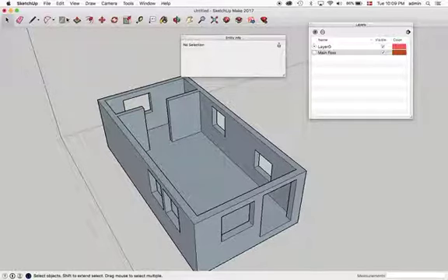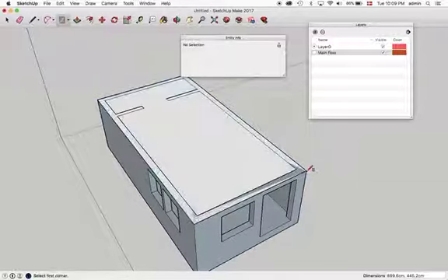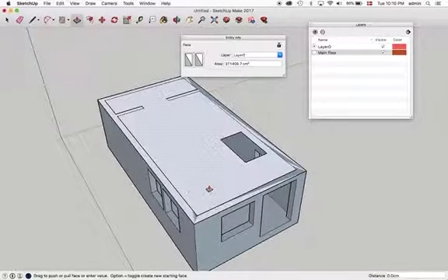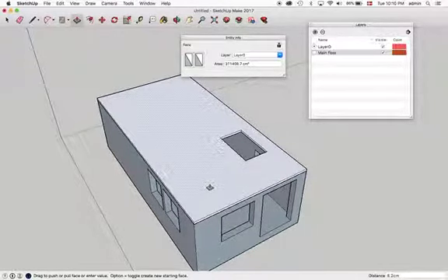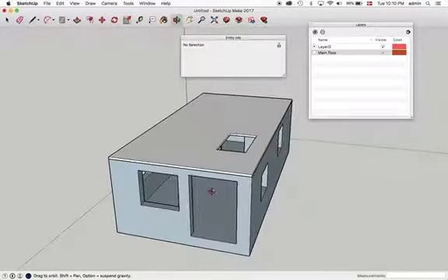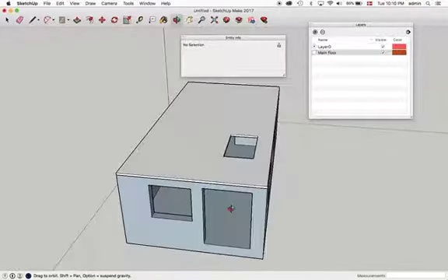Now I'm going to put a mezzanine area on the top. I'm just going to draw a rectangle across. I'm going to draw a trapdoor next to the door, I think, and delete that before I pull it up. So I go to the pull tool and pull it up a bit. I don't know how thick the floor should be, it doesn't need to be very thick really. Imagine it's just a wood floor. So now I have my mezzanine.